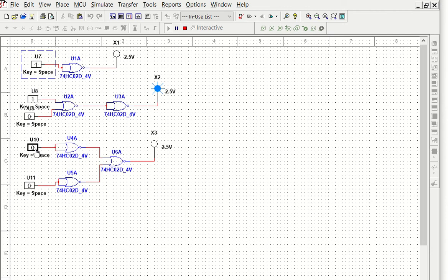If we consider the next gate, which is AND gate, only for the 1 1 combination is the output supposed to be high. If we take 1 0 combination, it is low. If we take 0 0 combination, still low. Let's take 1 0, still low, and the rest was 0 1. You can already check for yourself. So now our basic gates are complete.